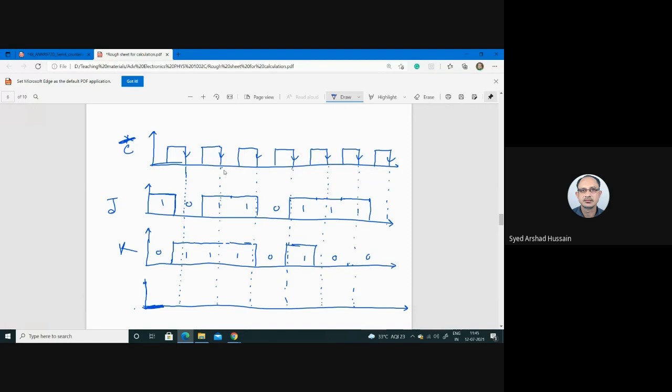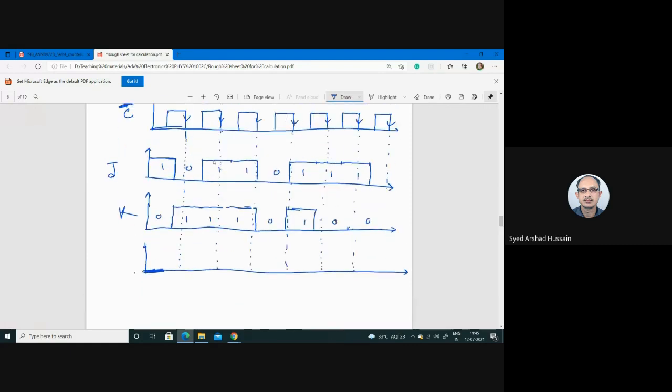Now, initially, your circuit is in, this is your output, মানে Q N, okay, or N plus whatever may be. So initially this is in reset condition. As soon as it will come here at the negative edge of the clock pulse, you will check what is in the input. You see 0, 1. 0, 1 means your output is again 0. So it will continue this same state up to here. Then again it will check. Here you see 1, 1.